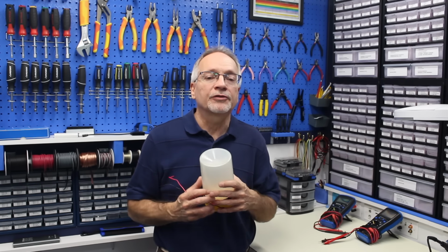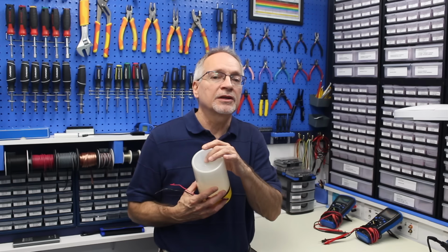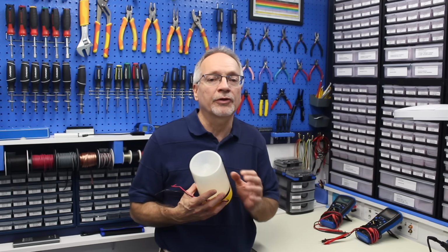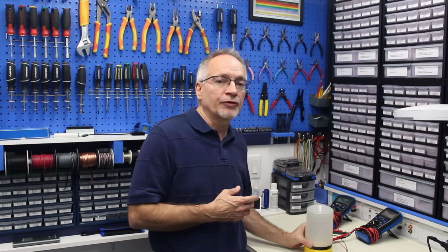Alright, now we're finally ready to start with our experiments, and for the first one we are going to be using the transistor I just showed you, the TIP120 Power Darlington, and we're going to be using it in order to drive this. Now this is just a 6-volt lantern, and it uses an incandescent bulb, so it takes a reasonable amount of current. You could not drive this directly from your Arduino, and so we're going to connect the transistor up to the Arduino and simply create an on-off switch.